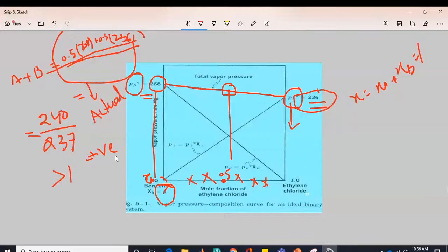Okay, let me go through some of its text. The distillation process in which liquid is distilled at a temperature lower than its boiling point. I mentioned why lower, because the boiling point gets lower. Application of vacuum pumps, suction pumps, etc. are used to reduce pressure. Now definitely it's a reduction of pressure of the liquid surface. Distillation under reduced pressure is based on the principles of simple distillation with some modifications.